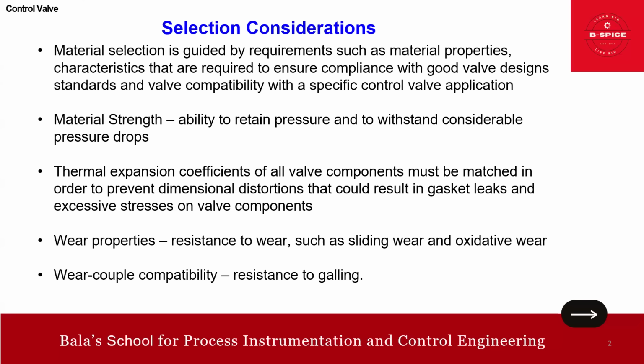Then we have wear couple compatibility, which is the resistance to galling. What is galling? Galling is a form of wear caused by adhesion between sliding surfaces. Galling in a control valve is an unexpected adhesion between two metal surfaces in sliding contact, resulting in frictional damage or scission.